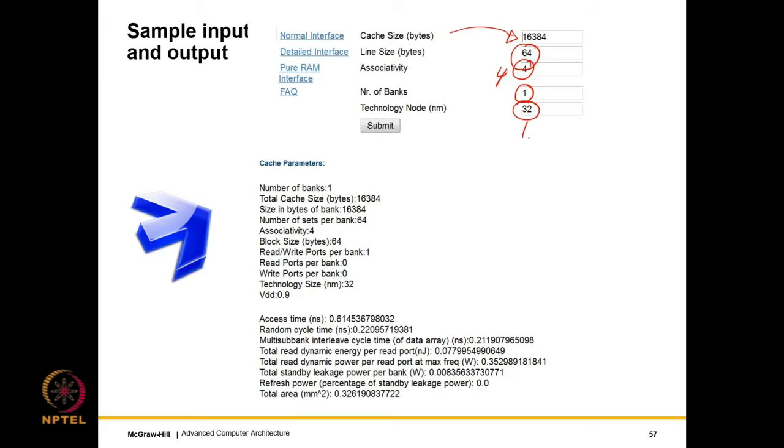So as you know, every 1 to 2 years, used to be 1, now 2, the technology node reduces by a factor of square root of 2. So given that each dimension reduces by square root of 2, the area of a transistor reduces by a factor of half. So this is how the technology nodes have been progressing. We are currently at 7.